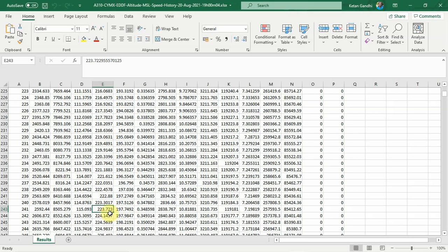If you calculate it, it is wrong. It's corrected by the calibrated airspeed, which is 197. Calibrated airspeed is a correction for the instrument and position errors. So the true speed is corrected here. This is the example we saw of how it is done.